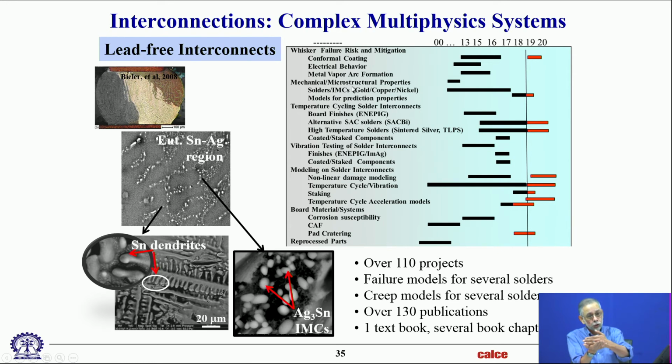So one is they cause shorts. The other is if I've got two of these solder joints with whiskers growing towards each other, when they reach a certain proximity, they'll start to arc, and that causes problems. Okay. All right. Anyway, so